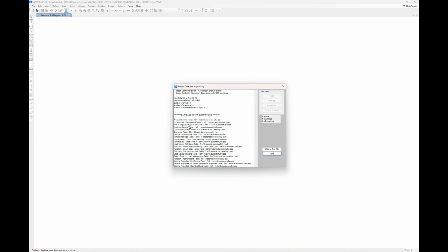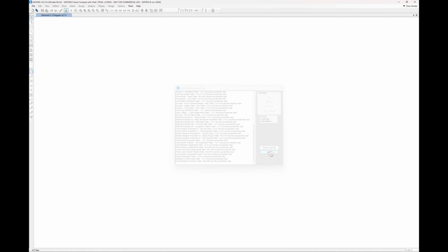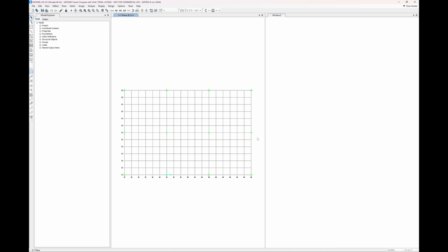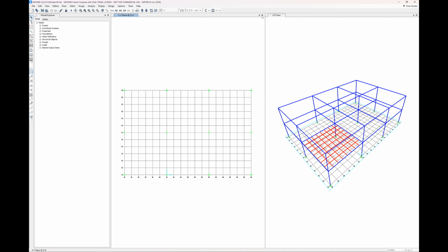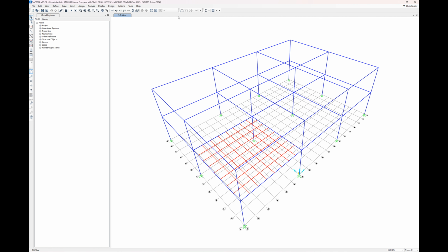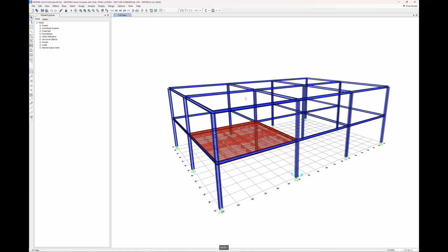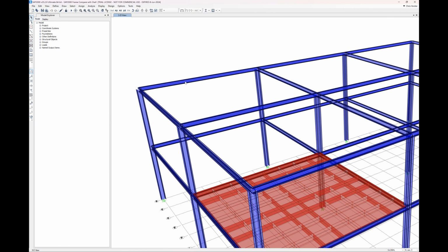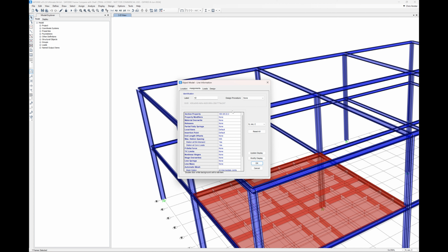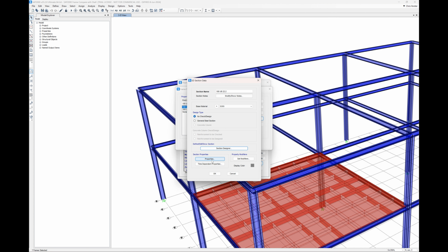So we can see once it's imported, 0 errors, 0 warnings, 0 informations, which means everything works. It's really robust. Everything should be 100% accurate. Beam orientations, end releases, supports, loads, material properties, section properties, load combinations, the works. So in fact, if we switch on the model extrusions here, we can see that it visually compares with everything we've got in GenFEA.